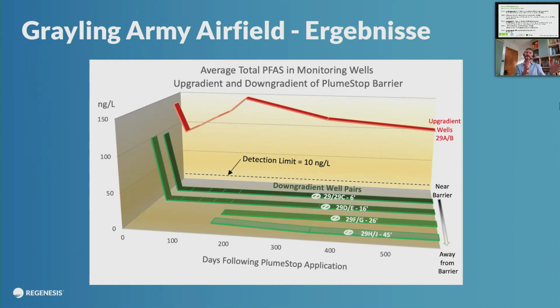And if they'd monitored earlier, what you would have seen is that those levels weren't affected immediately by the treatment, but as the cleaner water comes through and as we work through the back diffusing mass that will leave and attenuate, we then get down to those low concentrations.